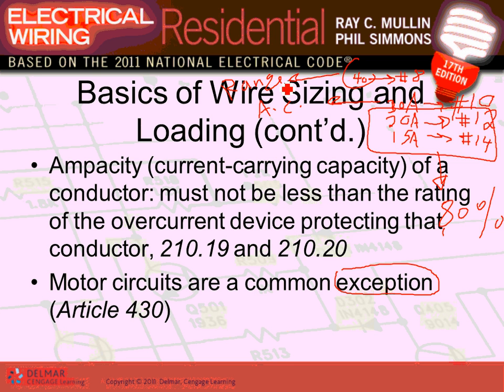Any comments, guys? Any questions about this? These are very, very important when you start circuiting. And when I say 40 amp, Matthew, I mean 2 poles, like these 40 amps. When I say 30 amps, I mean 2 poles. 30 and 40 are 2 poles, 2 of these. 10 and 20 and 15 are single poles. 1 pole, 1 circuit breaker. Any comments, guys? Any questions?